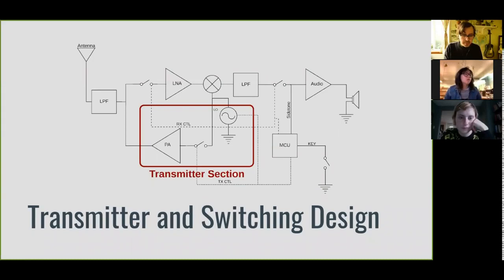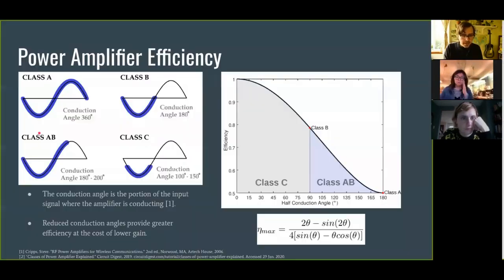Now, I want to be able to talk back to the station I'm listening to, so I might want to design a transmitter of some kind. So in this case, I just had the local oscillator switching into a power amplifier. So we had to do a little bit of a power amplifier design. You can't talk much about power amplifiers without mentioning efficiency. And this transceiver, it's for portable use. It's running on battery power, so it's a big important factor to consider.